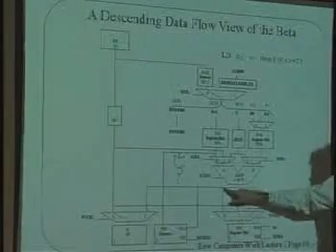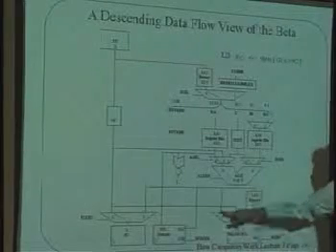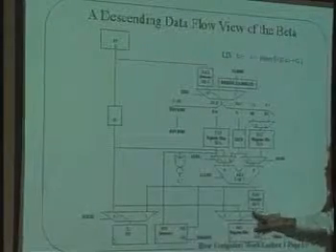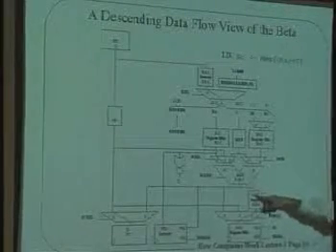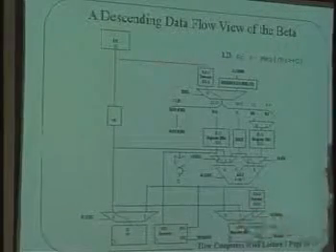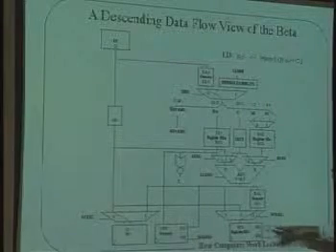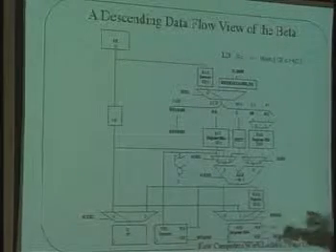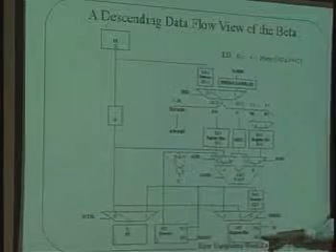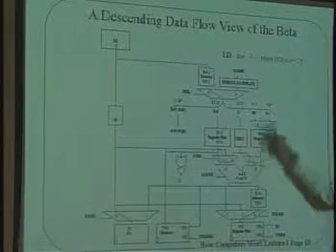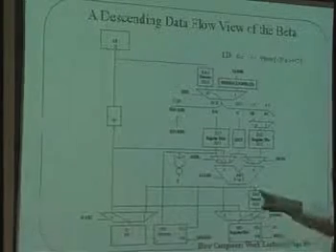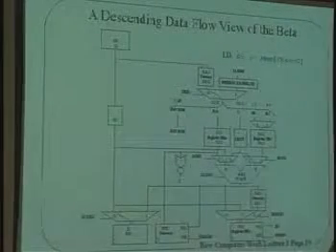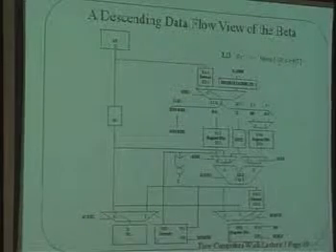That comes out here, and the value of what's inside of here, not that thing itself. You see, this would just write the contents of RA plus C if we chose this path. But if we choose this path, it says what is in the memory location pointed to by the contents of RA plus C. And that gets fed to the register file here. RC says where we want to write it to in the register file. This says we really want to do it. Clock goes off, bang, the load happens. Okay? So this is where we're doing the fetch here from the slow memory, the big slow memory.